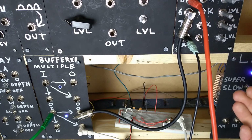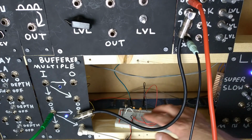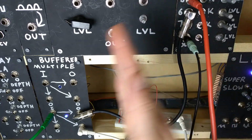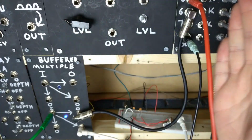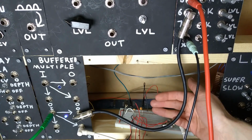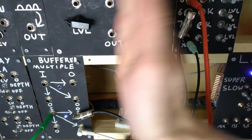Alright, so this is kind of fun, but it's not really that exciting. But what we can do is replace this resistor down here with a potentiometer, so that we can actually shift the cutoff frequency to where we want it. So let's do that and see what it sounds like. So I've got our potentiometer wired in, so now we can actually adjust the cutoff frequency.